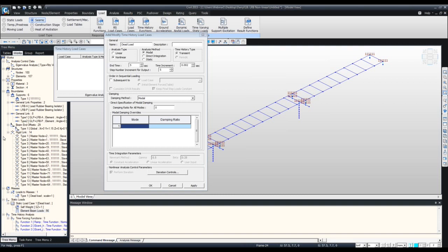Now the next thing we need to do is click OK or Add or Apply. Oh, actually, let me check the damping ratio real quick. Okay, make sure to change the damping ratio to 0.5. There we go. Now the damping ratio is there. You can click Add or Apply, and there's our first function.